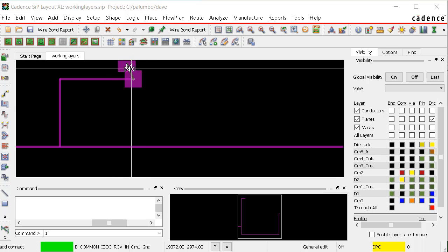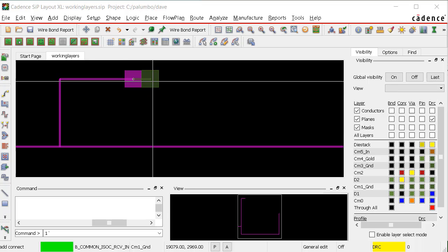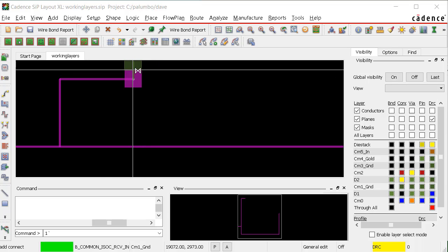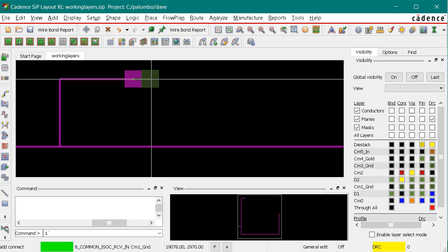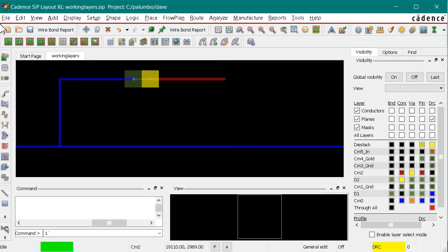As I move this second staggered via, it is snapping to 22.5-degree angles. So it makes it very easy to make sure I'm going either exactly horizontally or exactly vertically, whichever you choose. And I'll select this location right here so that we add our via exactly horizontally, and what we now end up with are two vias that are staggered by 6 microns.